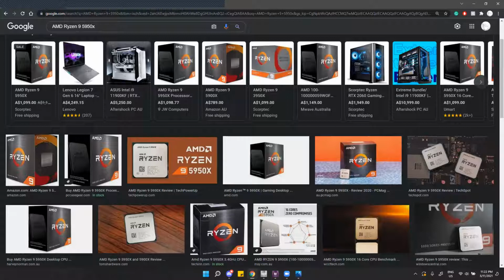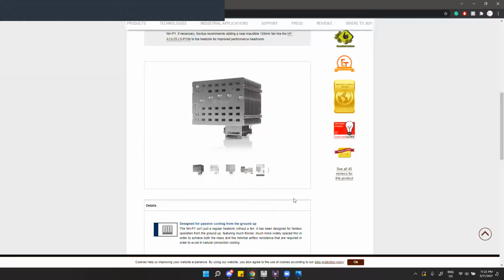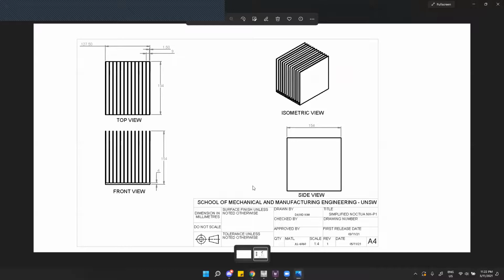Linking back to the simplification of geometry, this is the current geometry of the cooler, and this is a simplified version. It has been simplified greatly to allow for simple modeling as well as a good mesh, as certain geometries will yield lower quality meshes depending on the consistency of the surface of the model. For example, if a smooth surface is immediately followed by sharp corners, then the mesh will not be of high quality. The mesh will be decreased over time while using a hexahedral element size.